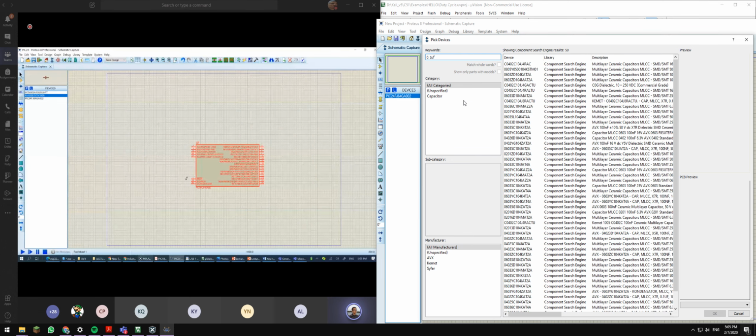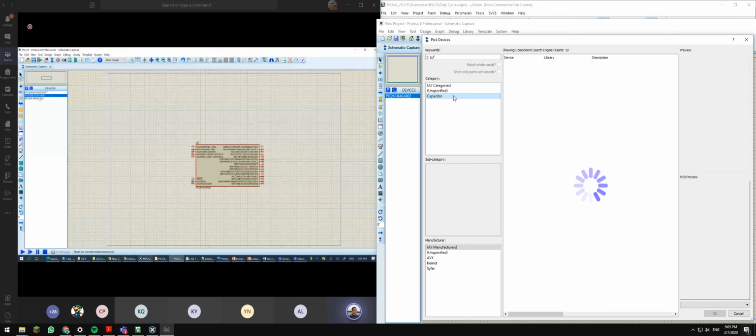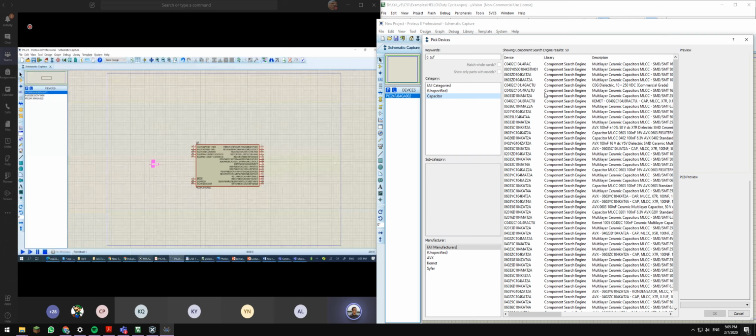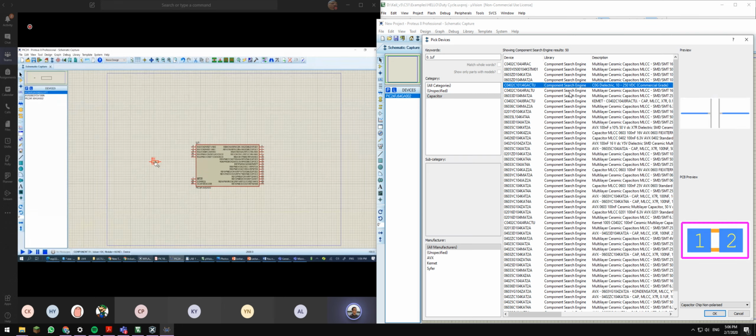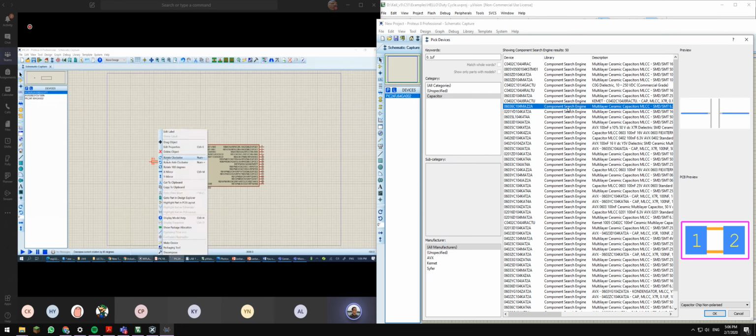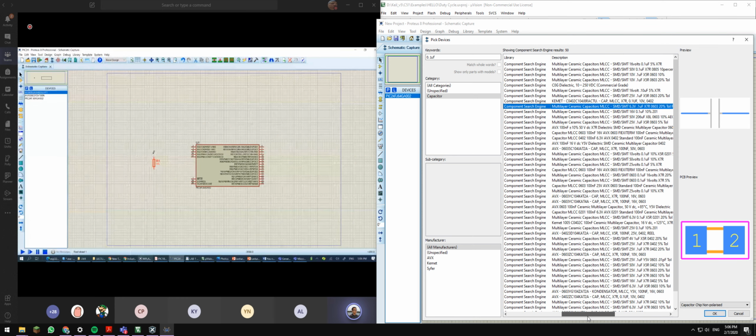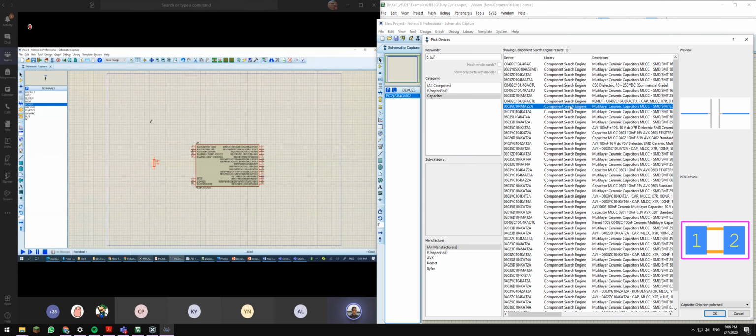So again, we need a resistor. This is a 100K resistor. Okay, this is the proper way of connecting. Although you can just directly put it to high, like what we did for the PIC 18, I don't want to do that. So that's why we want to do it more professionally, because you are always using PIC 24 later.